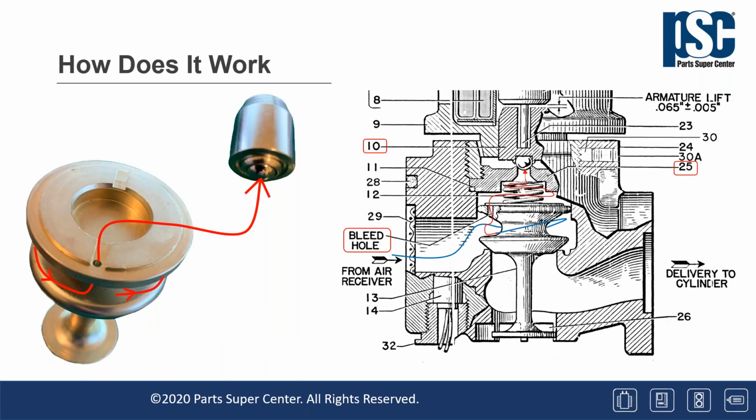That additional force helping to push the piston down is generated by the small bleed hole in the top of the piston. This hole allows the air trapped between the two lobes of the piston to escape to the area above. Since the air pressure acts in all directions, it will push down on the large surface area on top of the piston. The net effect will be a strong differential pressure in the downward direction from the air acting on top of the piston plus the bias spring above the piston. The forces acting between the lobes cancel each other out since the surface areas are similar in size.